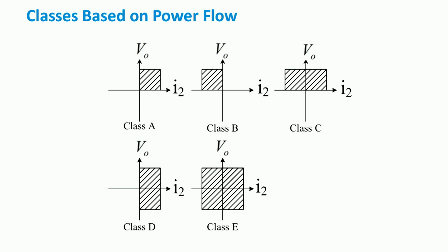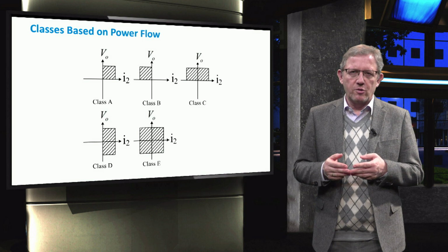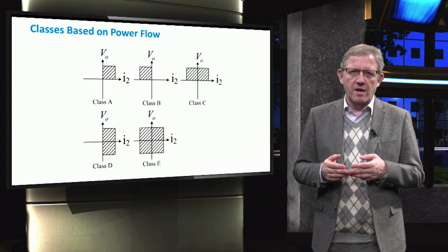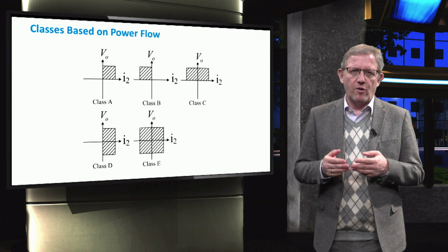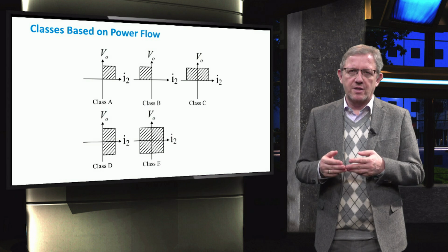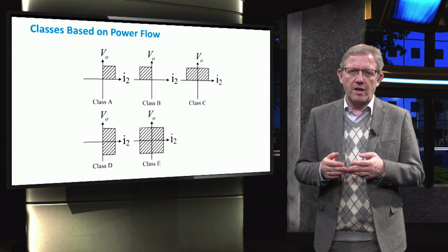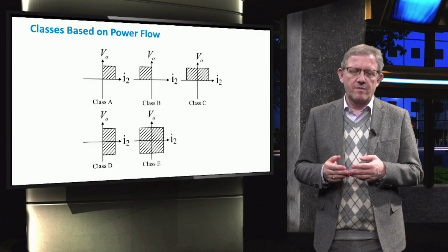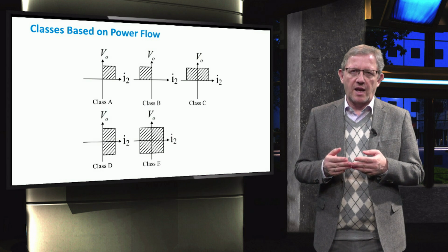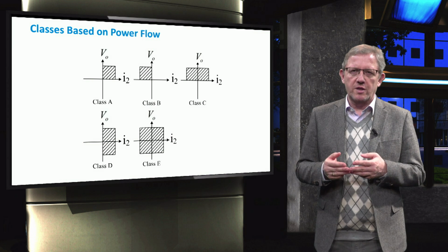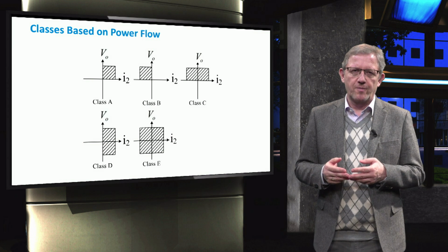However, Class E has a higher cost than Class C, which can offer all the necessary features required by the DC microgrid. This is mainly due to the fact that DC microgrids are operated typically in a fixed voltage polarity. Therefore, Class A, B, and C are the most suitable operating options for DC microgrids. In the next slides, we identify and discuss these classes for the previously introduced DC-DC converter topologies.